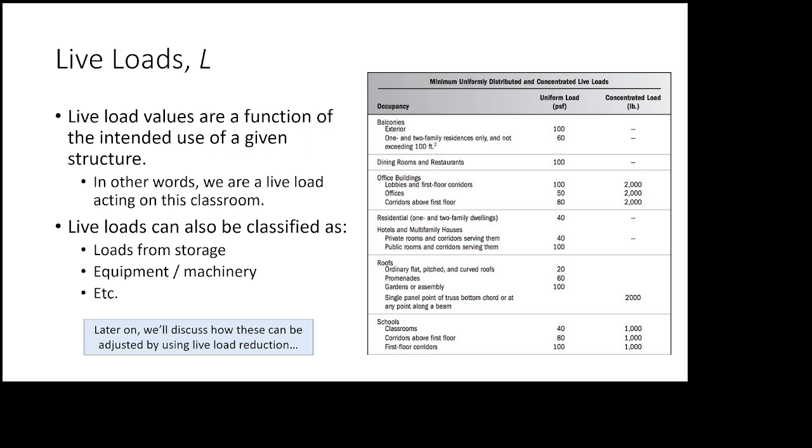Because it's more variable. I have more uncertainty associated with the live loads than I do the dead loads. Dead loads is all about just computing volumes and unit weights of materials and adding everything up. The uncertainty comes from stuff like, you've got an 8-inch slab, and they might pour 8 1/4. They might bump it up a little bit just to make sure they get their target depth, right? That makes it a little heavier, right? But that's what the factor of safety is for. That's what the load factor is for, to account for additional load, for uncertainties.